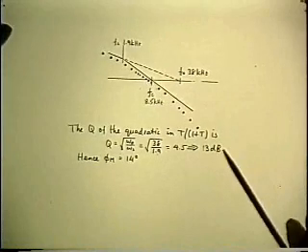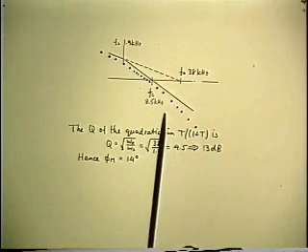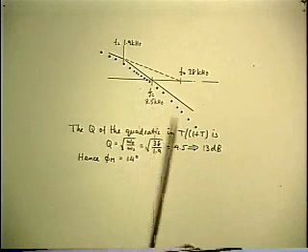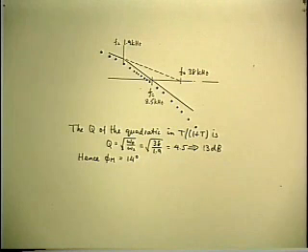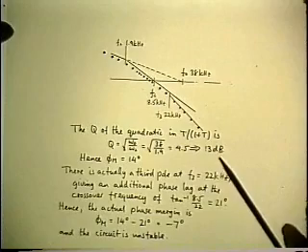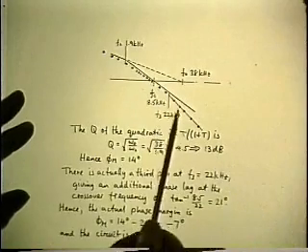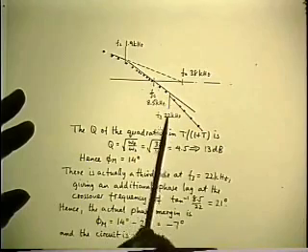And so when we measure the unstable loop by this technique, this is what we get. And of course there's a deviation this time. That's why it oscillated. But now we find out what the error was by doing the old eyeball least squares fit again, we discover that there actually is a third pole at 22 kilohertz.